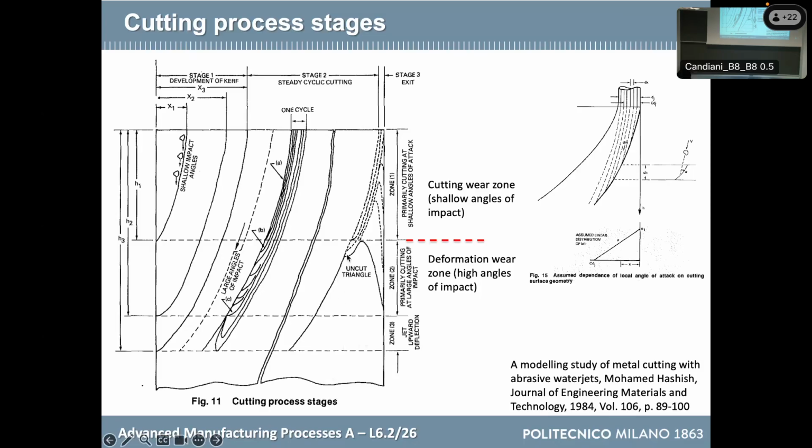If you imagine starting from this cutting front and reducing the feed rate, it will become vertical, more vertical, and it will be able to remove also this portion of material. If I don't remove it, my part will remain attached to the rest of the slab. And sometimes you can even use this phenomenon, because you can take the parts attached there, and then you remove the parts by hand.